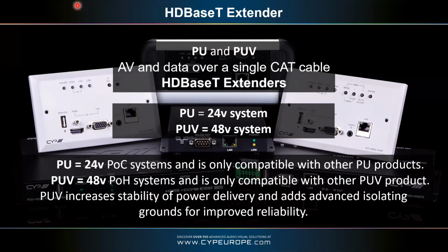So originally, I think every single HDBaseT manufacturer decided to go for 24 volt, because the price of the 48 volt PoE injectors was so expensive. Now, over the last 3 or 4 years especially, as 48 volt injectors have been more and more commonly used with HDBaseT, the price has come down quite noticeably. So now the PoE injectors are only a little bit more for 48 volt than they are for 24 volt.